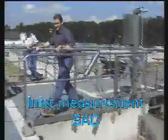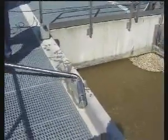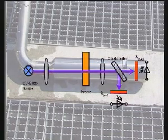In order to respond rapidly to varying inflow conditions, the organic content of the wastewater is continuously measured by means of the spectral absorption coefficient at 254 nanometers. For this purpose, a UV process probe is used. This probe operates on the principle whereby numerous organic substances absorb light in the ultraviolet region of the spectrum. The probe is directly immersed in the wastewater and measures the spectral absorption coefficient, or SAC for short, at 254 nanometers. In particular, in municipal wastewater, the SAC parameter has a very good correlation to dissolved COD.